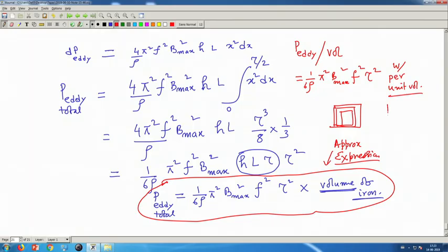Instead of that, you use plates, and the eddy currents will only be confined here, because the next plate is insulated from the other. If you do not use insulated plates, then the story remains the same, the eddy paths will be more. Are you getting? That is why the insulation is necessary.